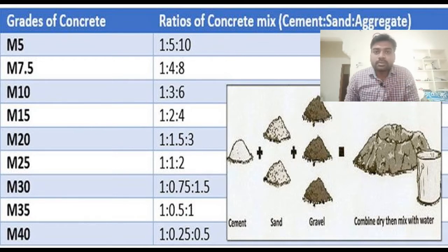Basically, the grades I have mentioned on the screen are achieved at 28 days, but practically, on site we do not cure for 28 days.